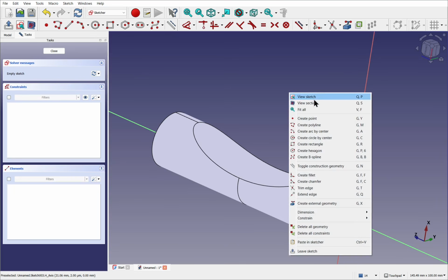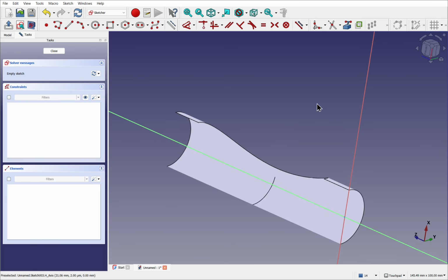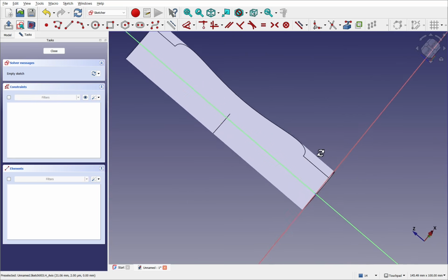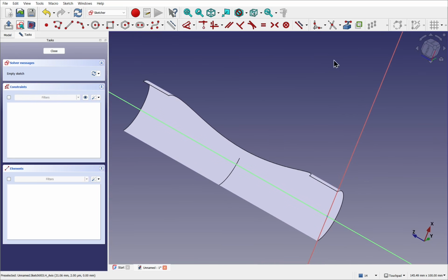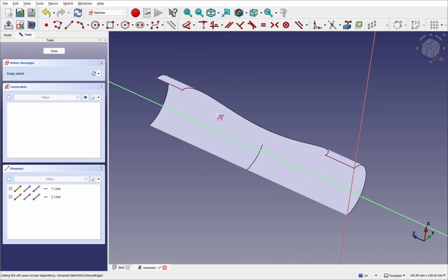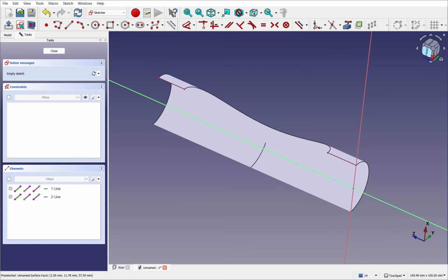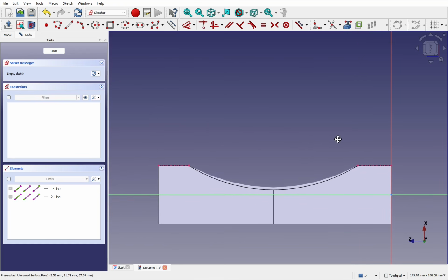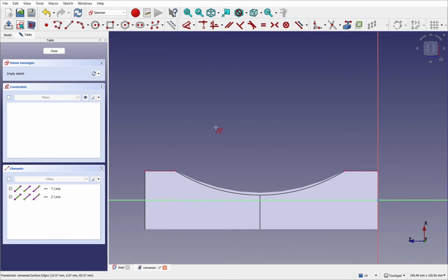Right click and use the fuse section. Gone through the center there. And that's external geometry. And I'm going to import this line and this line. And if we look to the front, we've got those two in there. Right click to cancel the tool.